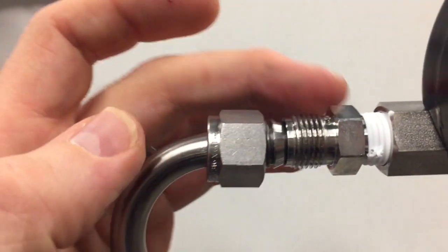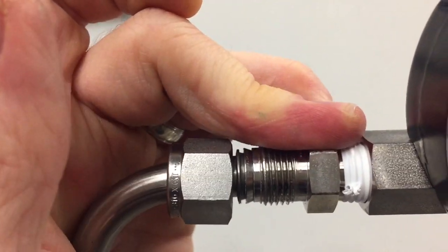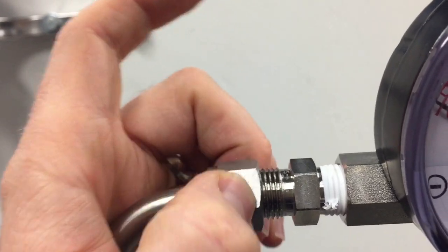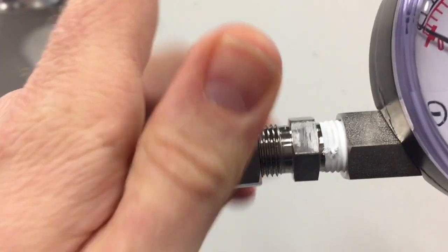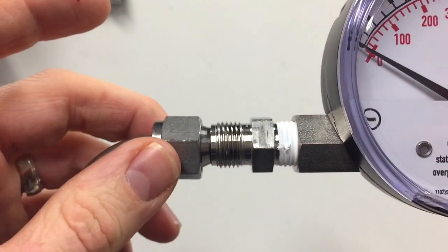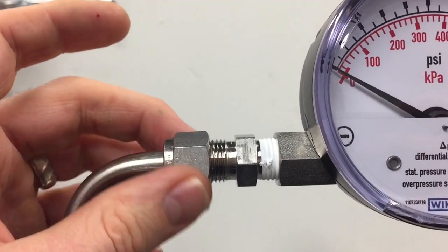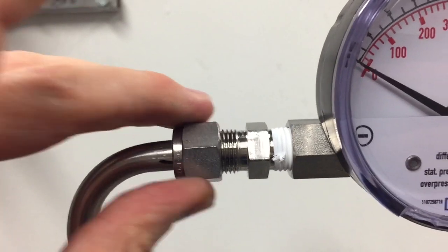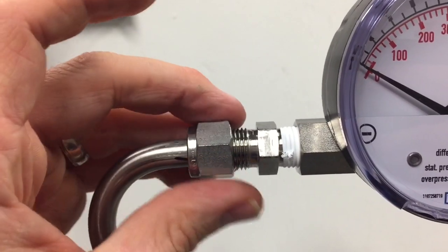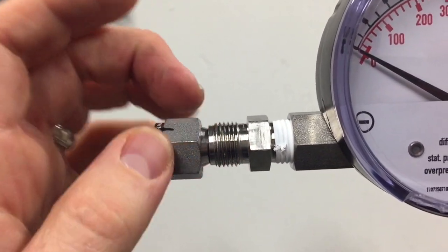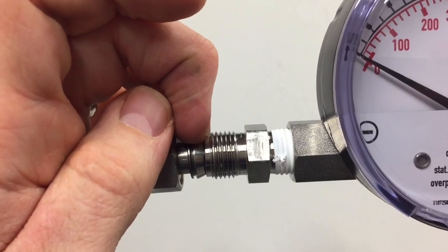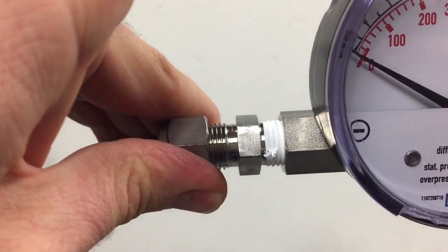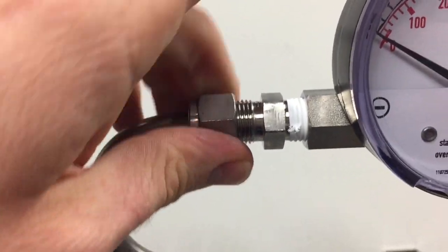And if you look here, it's not quite square. So there, I pushed it in, and we'll see if it threads on. There, it seems to be threading on a little bit better now. But what I wanted to point out is, if you do run into an issue where you're putting these back on and they don't want to go on with your hand, don't use a wrench to try to tighten them on when you're just starting them on. You can cross thread these threads and wreck them. So you want to make sure you get the first 3 or 4 threads on with your hands.